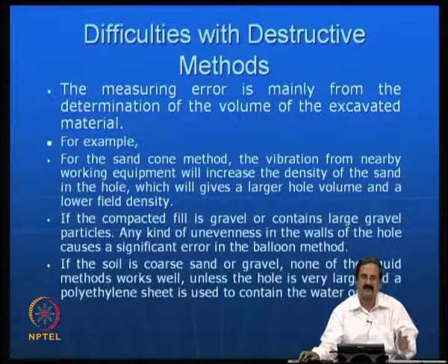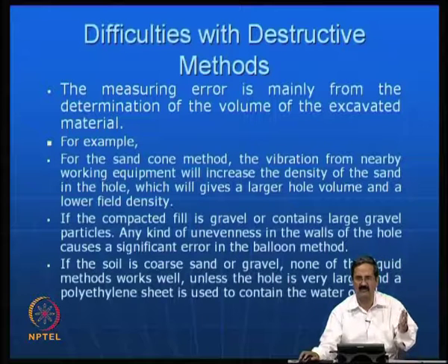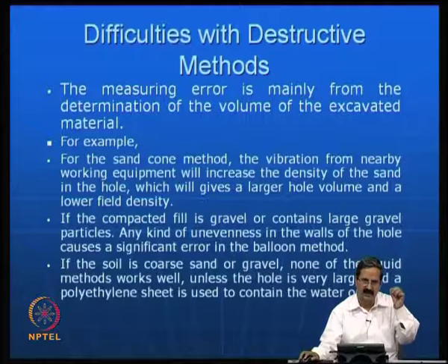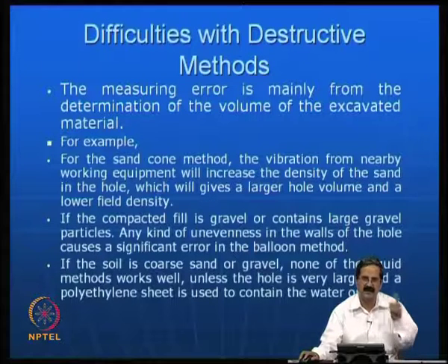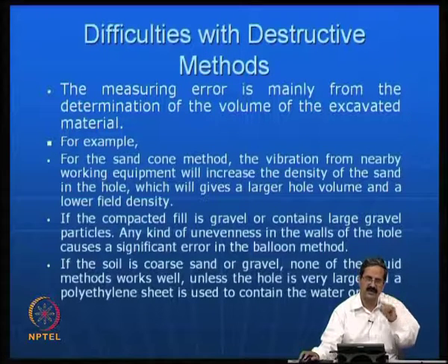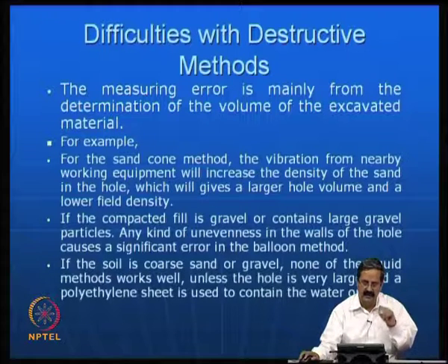Otherwise, all these methods are useless, because everything is volumetric here. So one should be very careful in volumetric measurements, even in the lab itself. First of all, one should be very careful in getting the compaction curve properly, and you should also understand the sensitivity of the compaction curve to water content and volume changes. Once you know that, then in the field it becomes much better.